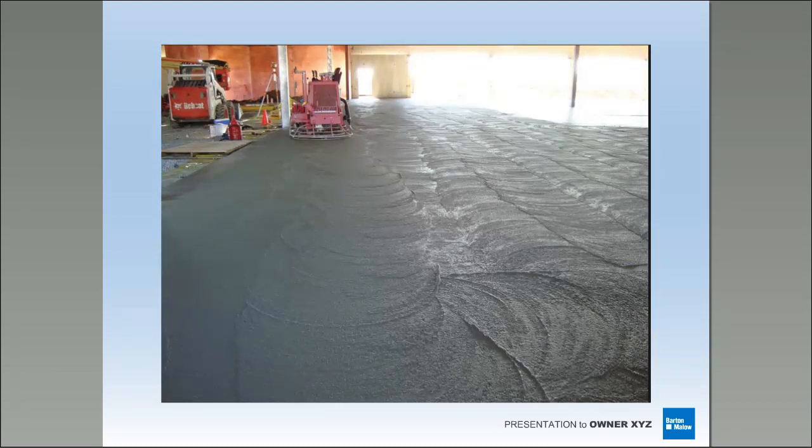I'm checking myself here. Okay, here's the panning process, okay? So the pan machine typically breaks open the floor and gets it prepped up for the combo that's going to follow, and then the blades after that. If you're seeing this on a project, pay close attention as a polisher or a place and finisher. You don't want to see these windrows, all right? You don't want to see this knotting in these areas where they're turning. All of this is telling me that they broke it too early.